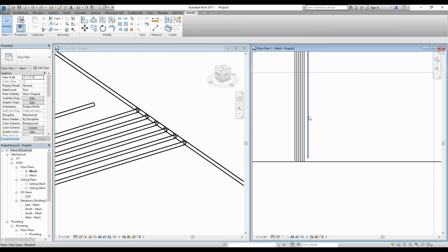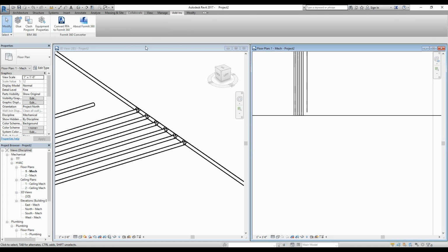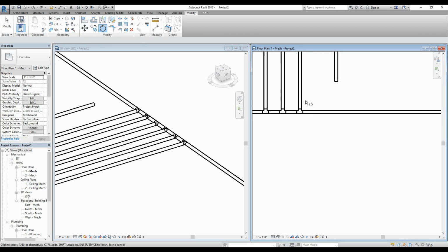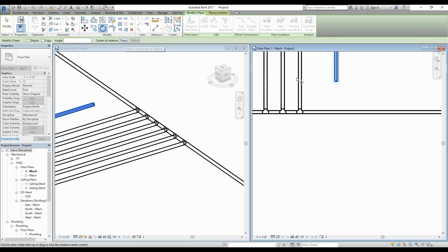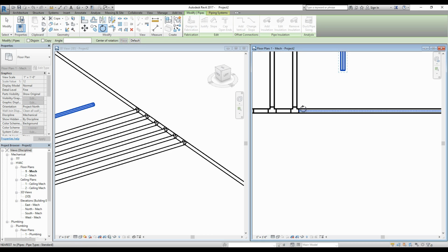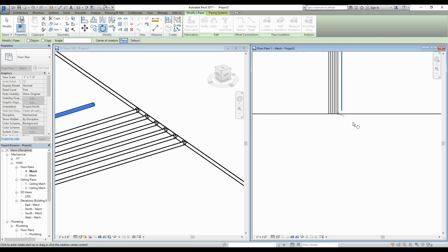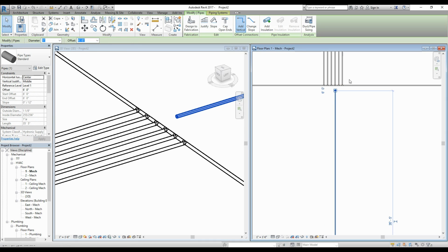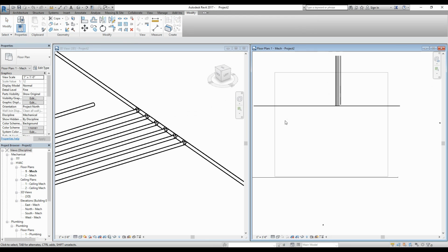Pretty simple. If I wanted this rotated around a certain point, I have to click this button first. Oh, you have to select your object first, I guess. I have to place this center where I wanted it, and then I can rotate this pipe. You have to click it once, and then you get the preview of where that goes. You can also type it in. If I want it 180 degrees, went 180 degrees around that point. Pretty easy.